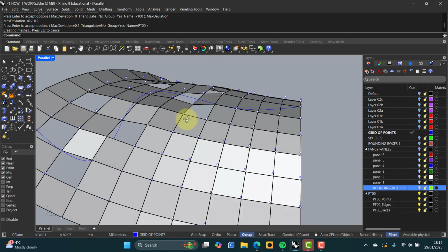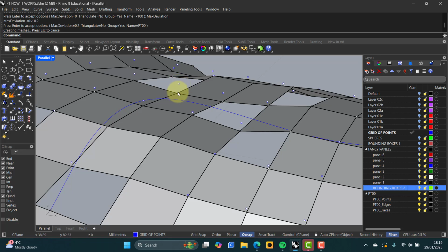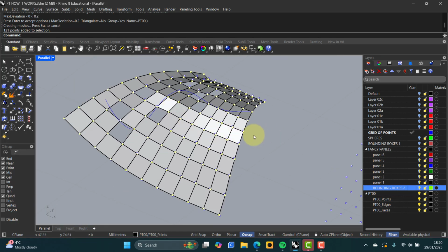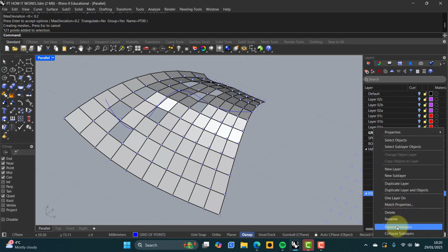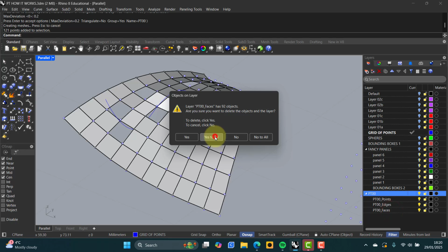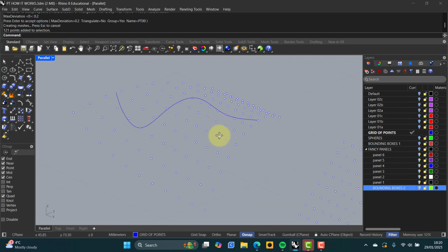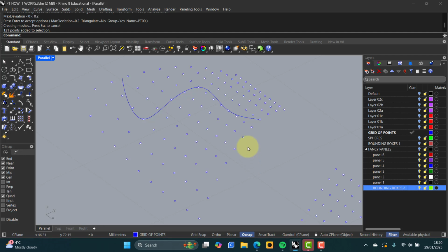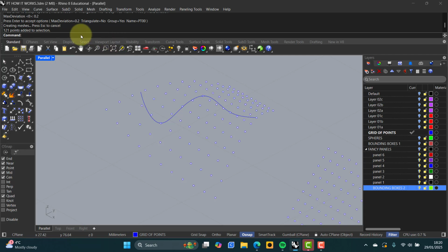We've got crumpling going on here because you can see just how far it's had to move the points. So the blue points were our original ones, the black ones here, these are the new points to try and get more of these planar panels in. Okay, and this is why you don't see many square panelled curvy buildings. Unless you set up the geometry so that it's all kind of concentric and offsets of curves, you just can't do it. So that's why you end up with triangulation.